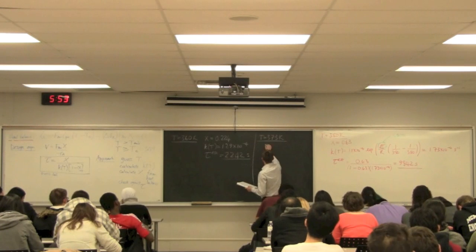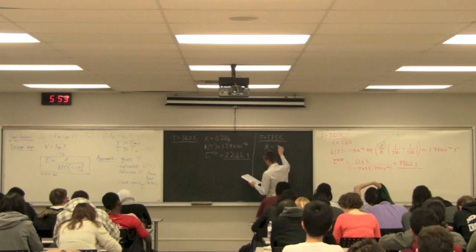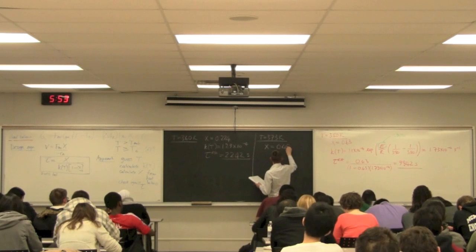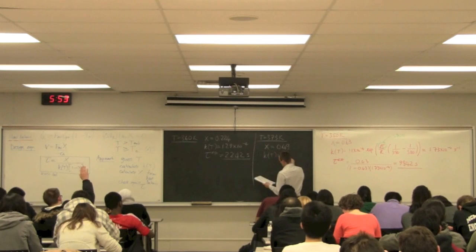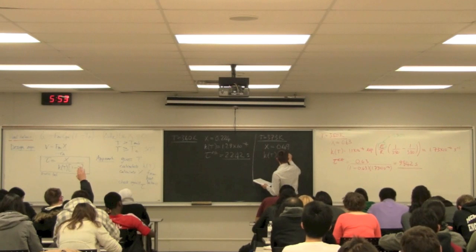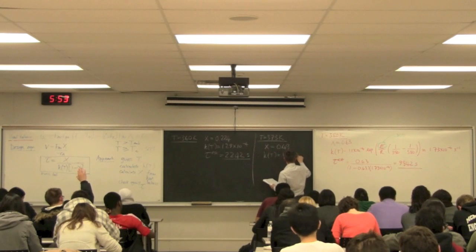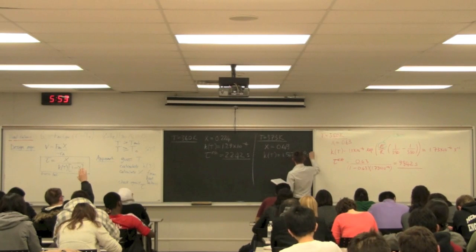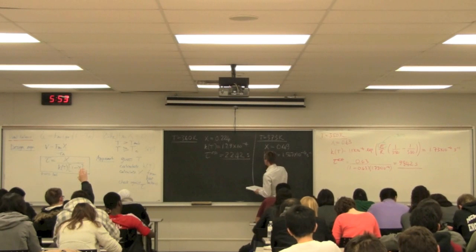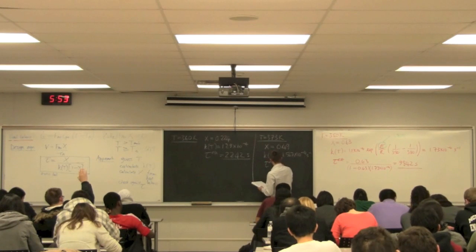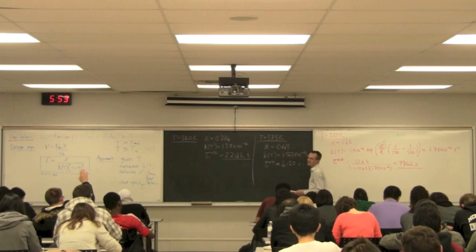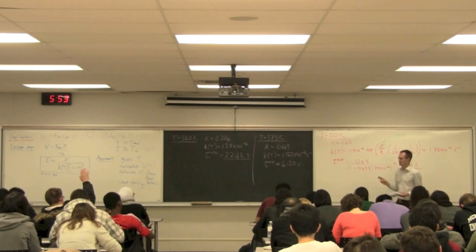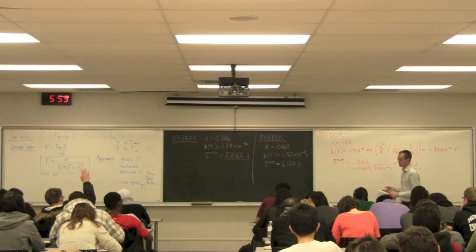There you find the conversion to be 0.49. The K value at that temperature is 1.567 times 10 to the minus 4 seconds to the minus 1, and my tau estimated is equal to 6,120 seconds. That's good enough, given how much this is changing for very small changes in temperature.